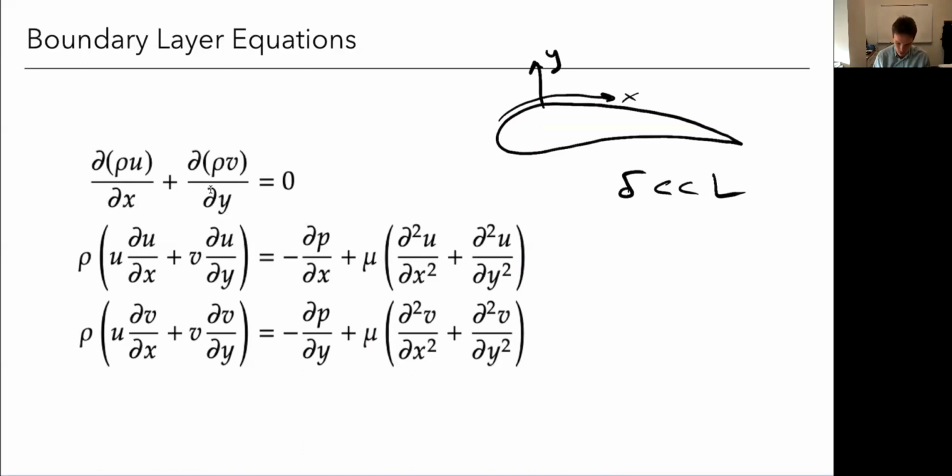If that's the case, then we can look at just this continuity equation, and in every case we're going to look at just orders of magnitude. How do things change in relative magnitude? So density, the magnitude is going to be the same. U, what's the magnitude of U? Well, we could use our edge velocity, for example. So if I just take this equation here, I could say from a scaling point of view, U is going to be proportional to my edge velocity. As that increases, I expect my U component in the boundary layer to also increase. And x is proportional to the length.